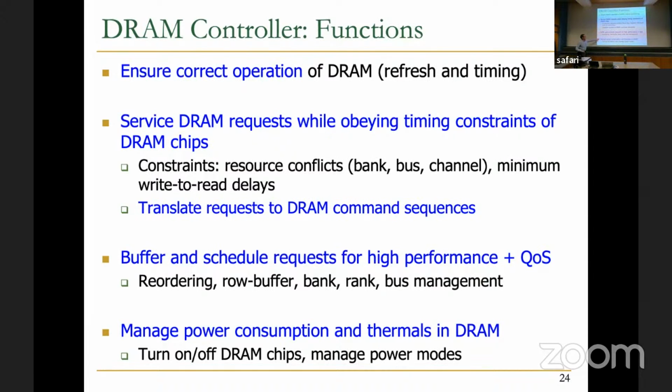Okay, so how do you manage power consumption and thermals? Do you turn on and off DRAM chips? Do you manage the power modes? There are multiple power modes, as we will discuss. This is an area that needs actually a lot more research going forward, in my opinion. We've discussed the idea of voltage scaling, for example, voltage and frequency scaling. Those are ideas that need to be employed, but there needs to be more in this direction.